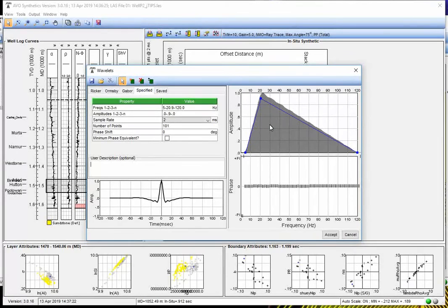Okay, so we've just put in a few points here. Now I want to add some data points to give a little more specificity to this particular curve. So I go to the icon over here, this is add specified point. When I click on that, then I can just come over here and digitize on that screen wherever I want it. We're not going to worry too much about it. And I can plop in a whole bunch of those points. If I want to get rid of a point, I hit the delete button over here, and I come to one of these points and I hit delete, and it simply removes this point. This is pretty standard behavior in a lot of point and click type things.